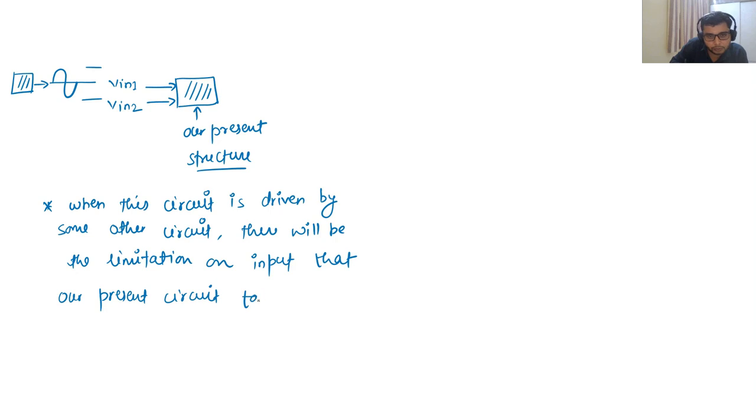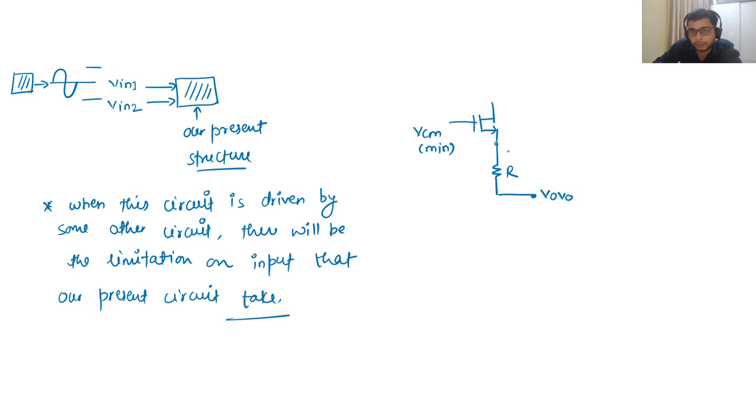Okay, so you do some homework on this and you will understand what these resistors are doing. These resistors are nothing but creating some common mode limitation here. So VCM min is higher due to this resistor. Because here we already have the minimum overdrive value of 0, and here we have this drop of I naught R in DC condition. So this voltage minimum value is a little more, by a factor of I naught R.